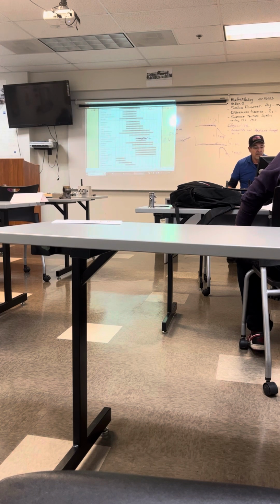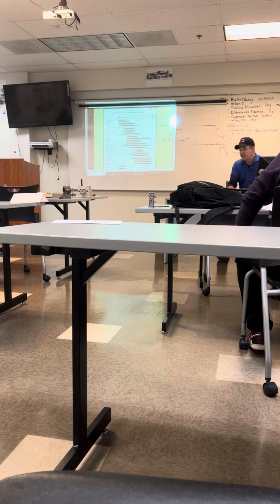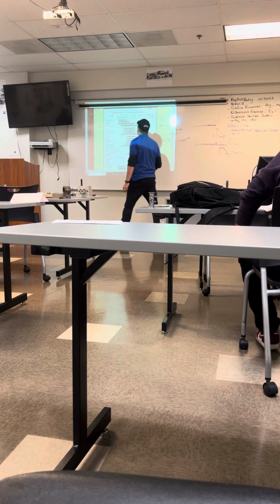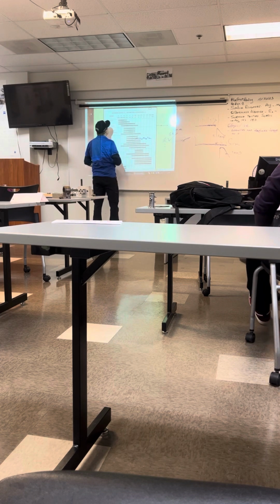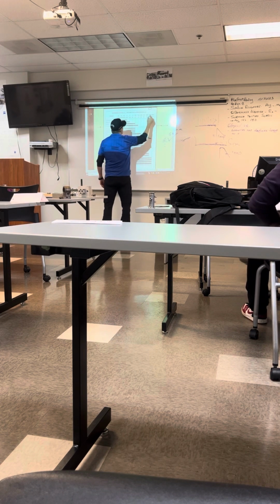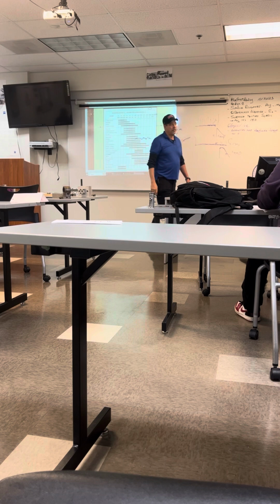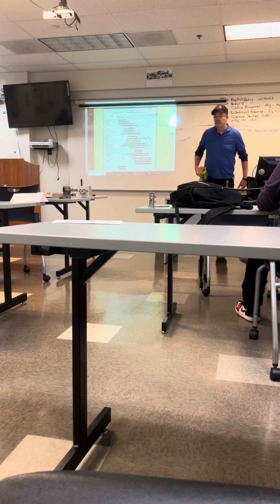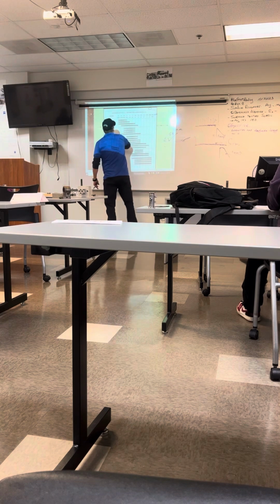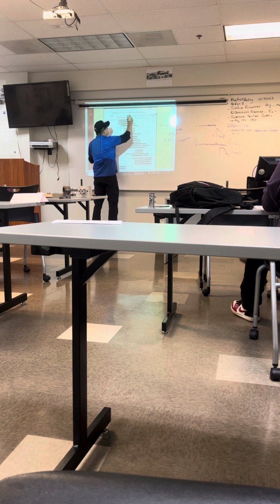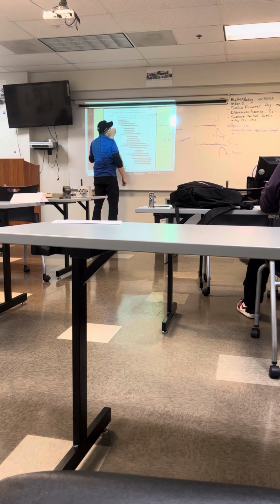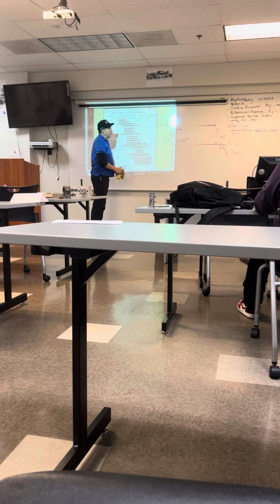Just to go quickly about it, here they indicate the average roughness. Here is metric, and here is inches. Right? For example, 3.2 micron is equivalent to 125 micro inches. Is that right? Or millionths of an inch.